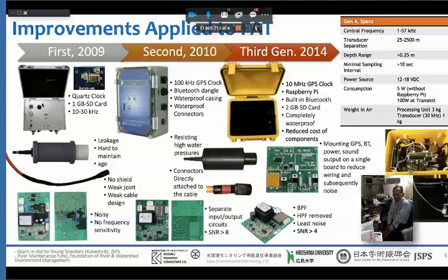And if you've ever worked with an analog system, you know that each piece of cable acts like an antenna and introduces more noise to the measurements. So for the data to be meaningful, the signal to noise ratio requirement for the system was about 10, 12, or even 15 decibels. So anything below that had to be discarded.